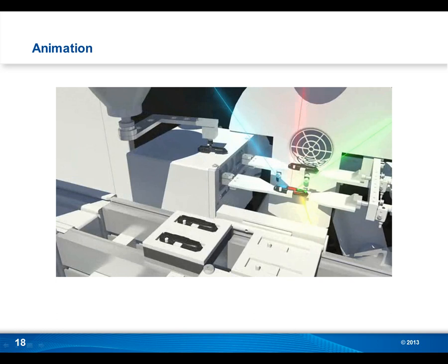Yeah, so here on the screen, before we roll the tape on this, you see a representation of what the inside of one of those LDS machines looks like, laser direct structuring machines. So here, represented through multiple different colors, we have various different lasers that hit a part all at the same time. So we really start to wrap the circuitry around this entire part simultaneously. So this is a high-value manufacturing machine that we see here.